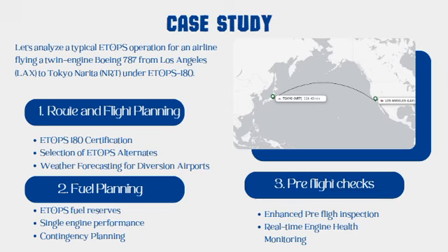Single engine performance. Since ETOPS operations require aircraft to be able to divert on a single engine, fuel calculations are adjusted for single engine flight, accounting for lower cruise altitudes and possible higher fuel burn rates. Contingency planning. Additional fuel is added as a contingency buffer for unexpected headwinds, potential holding patterns, or reroutes due to the weather at the destination or alternates.